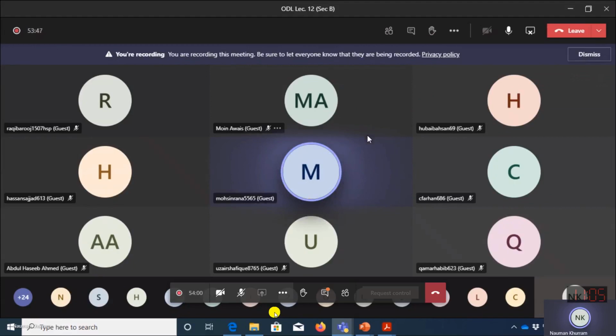It means that our assumed slenderness ratio is just to select a section. So if the actual slenderness ratio is more than the assumed value, it will not affect the selection of the section if it is satisfying the capacity. We only have to satisfy that the overall slenderness ratio should be less than 200, the section should be locally stable, and the capacity should be more than the factored compressive force.